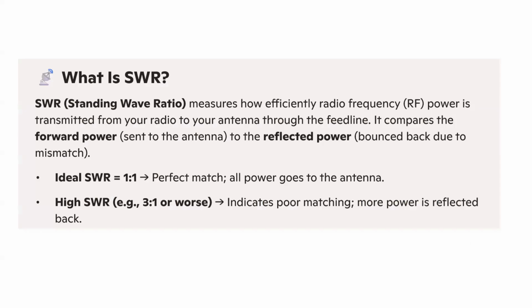The ideal SWR is 1:1, a perfect match. A perfect match is not required, as we can talk about. High SWR, let's say 3-to-1 or worse, indicates poor matching and more power is reflected back.